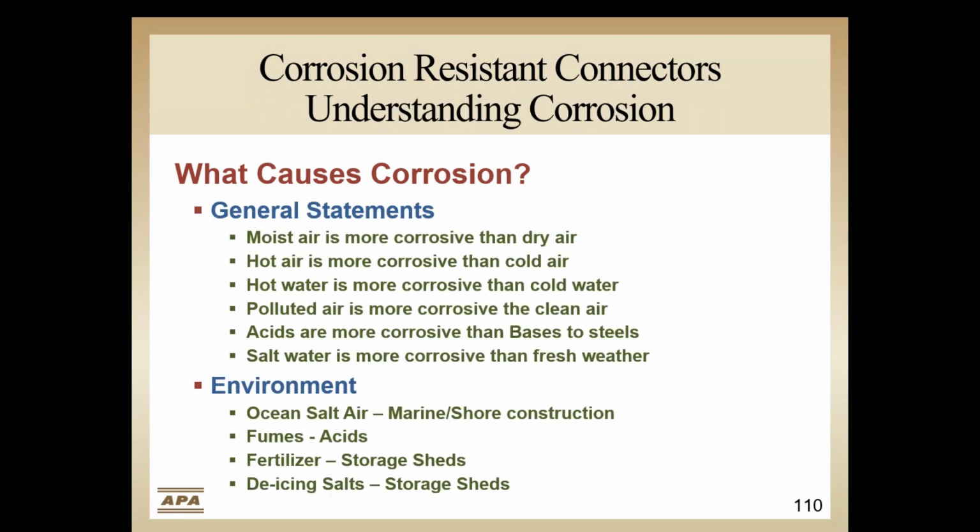The fact is, corrosion does occur, and almost all materials should be expected to deteriorate with time when exposed to the elements. Although all metals shouldn't be expected to corrode at the same rate, there are some statements that are generally accepted as facts. Moist air is more corrosive than dry, hot air is more corrosive than cold, hot water is more corrosive than cold water, polluted air is more corrosive than clean air, acids are more corrosive than bases, salt water is more corrosive than fresh water, and stainless steel will generally outlast ordinary steel. This is where the designer needs to evaluate the environment to determine what conditions exist when specifying a connection.